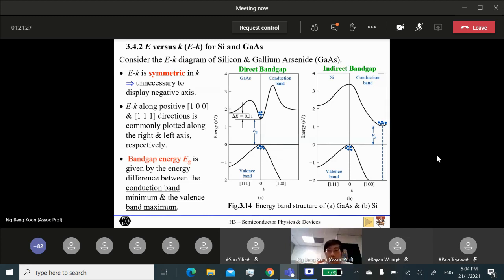The other thing you expect to be conserved, for elastic collisions particularly, is momentum. So in a semiconductor like this, if you have electrons in the conduction band, that's like before impact, and the electron coming back down to the valence band is like after impact. You expect conservation of energy and conservation of momentum to be satisfied for this process to occur.